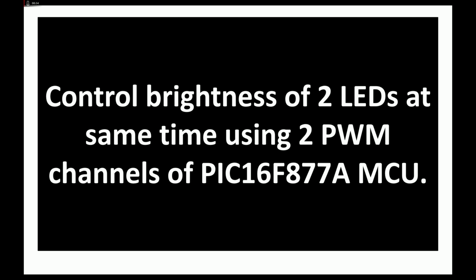Then we will program it in such a way that one LED will start from the off state and keep on going brighter. Once it becomes brightest, it will start all over again. At the same time, another LED connected to the other PWM channel will start from the brightest, then go dimmer, and finally go off. So this will be the demonstration of using the dual PWM channels of the PIC16F877A simultaneously.